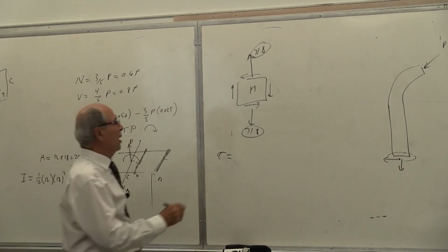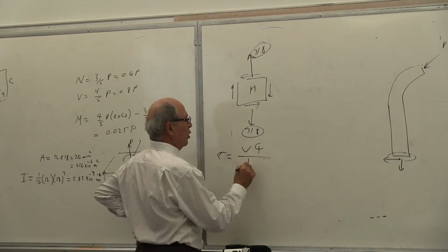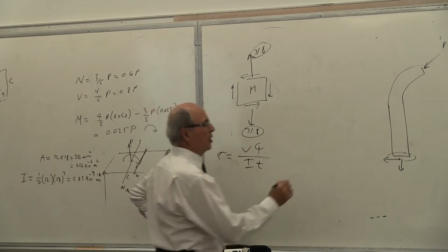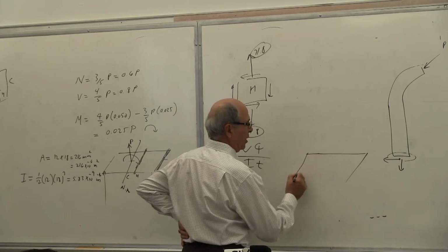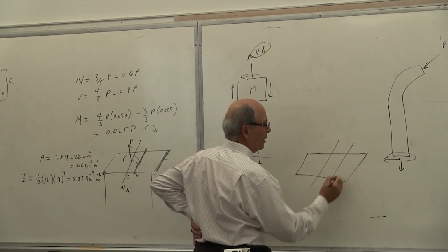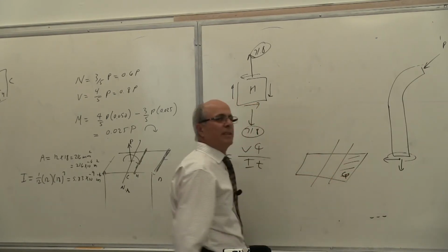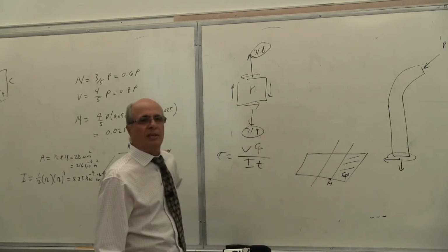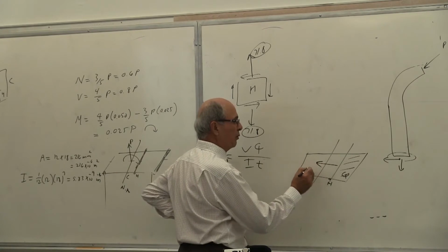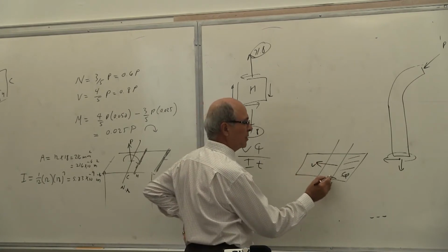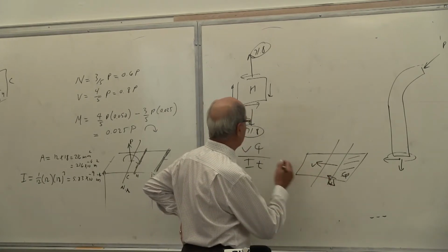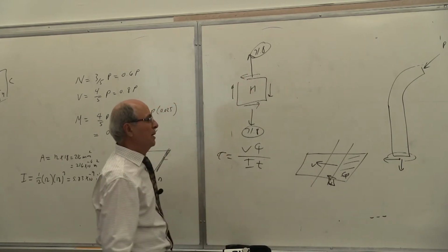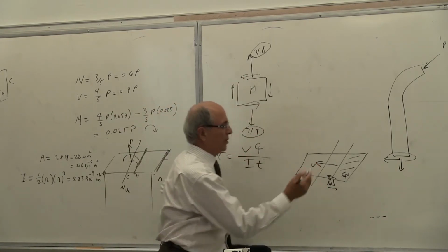The tau equal to what? VQ over IT. Where are you? Now, here is what we discussed before. You need Q of that, yes or no? Because H is here. Is that correct or not? Yes? The shear force going like that, that's your shear force. The shear stress going like that, which you can see, I put it that way on the top. On the bottom goes like that, etc., etc.